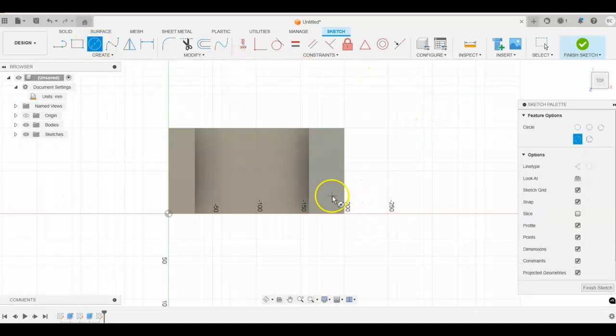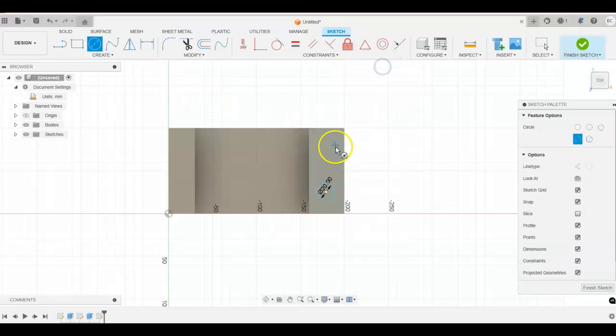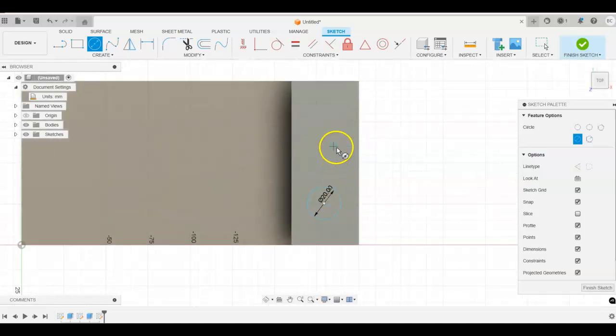So let's go ahead and create the circle here. We know from looking at the top view that these are also 20 millimeters. So let's click 20 and enter. And I'm going to right click, repeat here. Now, again, I want these two to be constrained. So I can come in when I'm doing my geometry. Now watch carefully. I can pick up that line, and you see that dotted line? That's going to create a relationship with these particular features.